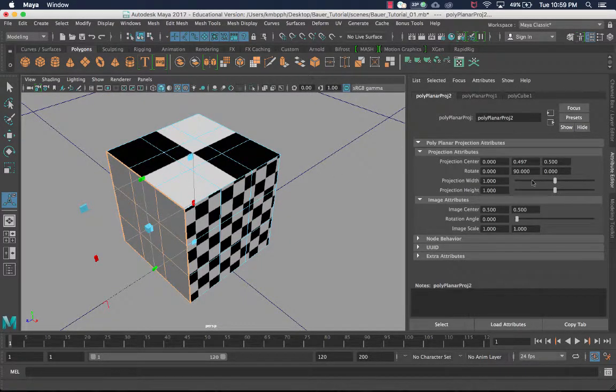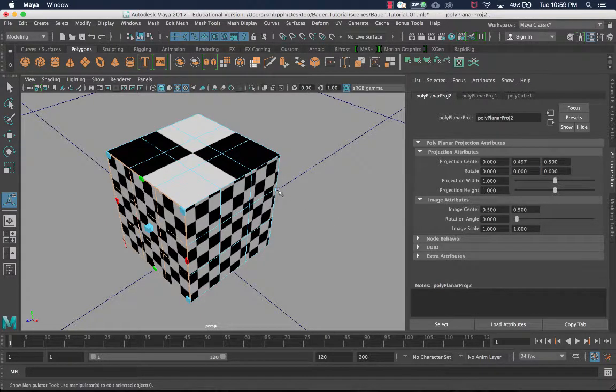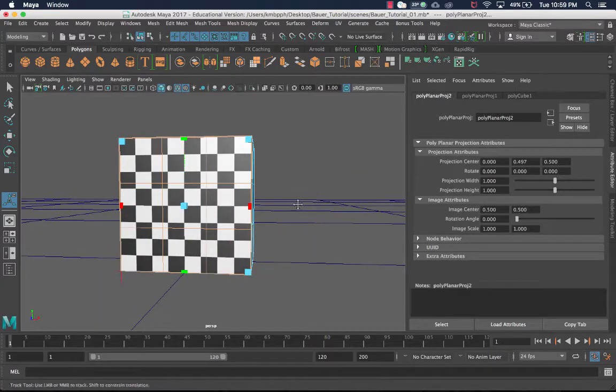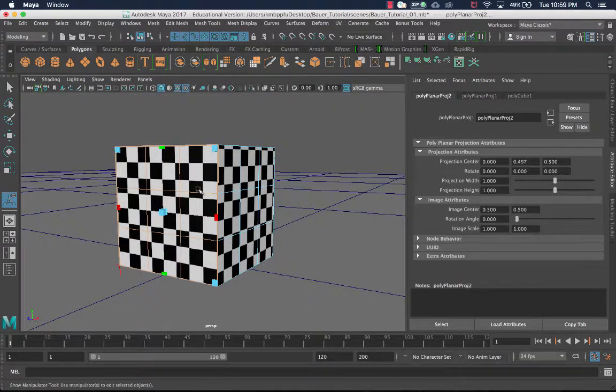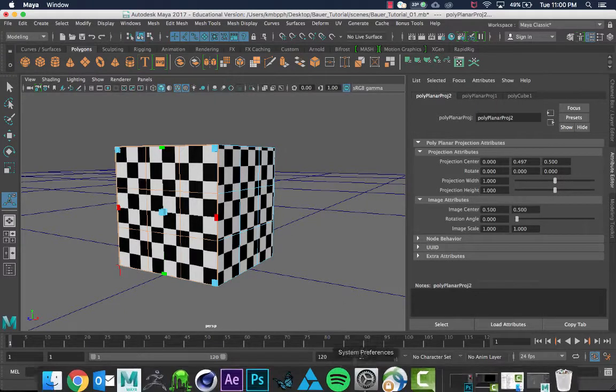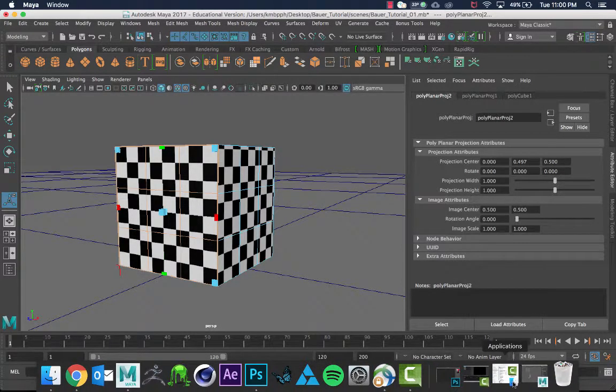So in my attribute editor, where it says rotate, the first thing I'll do is just take that 90 out, and we'll see if that works. So I'm going to set that to 0 and click enter. And you'll see that that made a change, right? So now that looks correct. It looks like that axis is sitting right on top of our plane. Those UVs, this side now looks exactly the same as the other side that we had worked on, which means everything is being projected correctly.